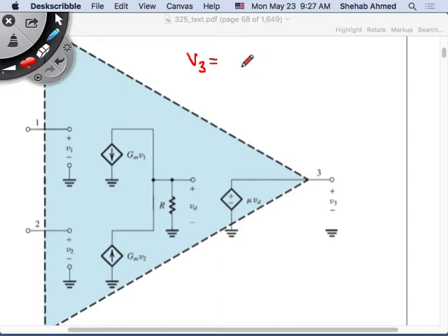It's a gain times the differential voltage, sure, but this is a specific op-amp now with a different equivalent circuit inside. I gave you a simple equivalent circuit with one dependent source. Now they're giving you this example with a different equivalent circuit. Remember we said that we have a very simplistic equivalent circuit that we introduced in chapter 1 and different variations of it, and then we have more complicated equivalent circuits. So here, V3 is equal to mu Vd.